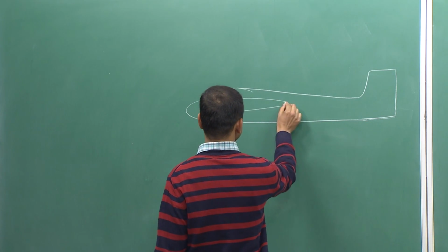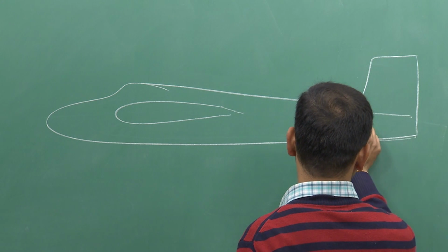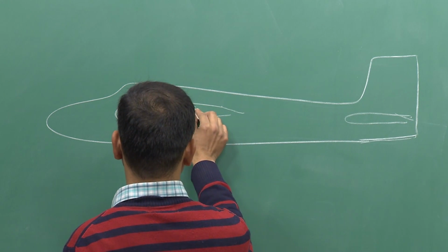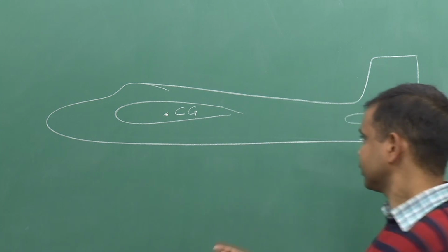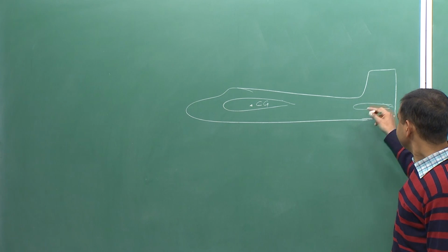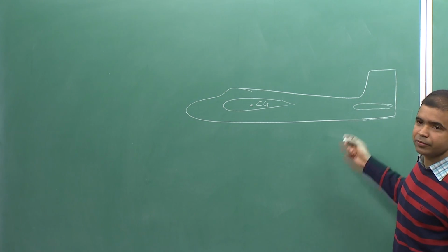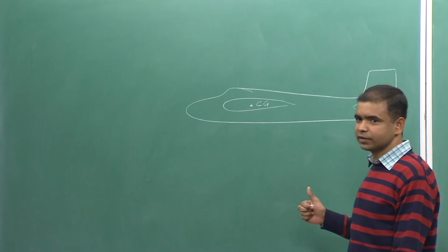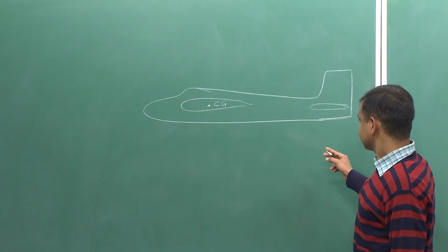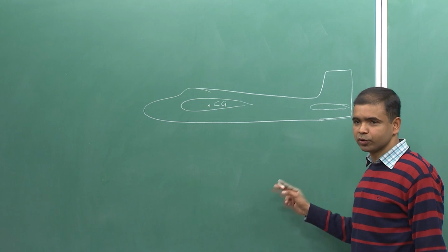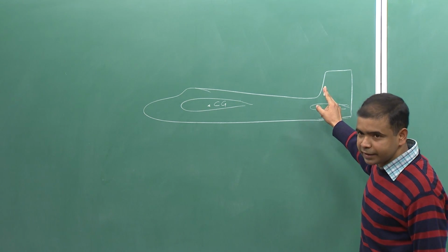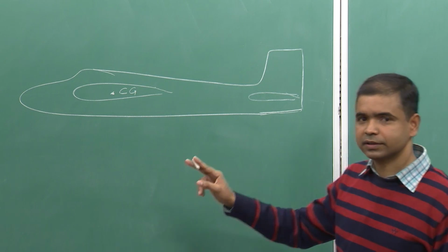this is our aircraft. For a positive value of beta, this surface will feel a force outward in this board, and this will give a positive yawing moment. So, Cn beta will be positive, or the contribution of this vertical tail is positive toward the Cn beta.